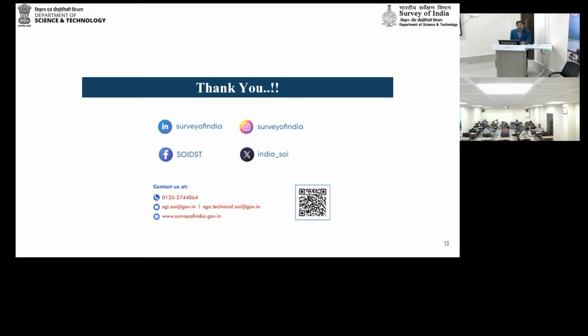No. This CORS network is for horizontal accuracy, meaning XY, and RL is the Z parameter. We are also in the process of establishing a geoid model for the whole of India. Currently 60% of India has a geoid model. After getting the geoid model for the whole of India, you can get the RL of any point by simply using a GNSS observation, meaning CORS will be used.